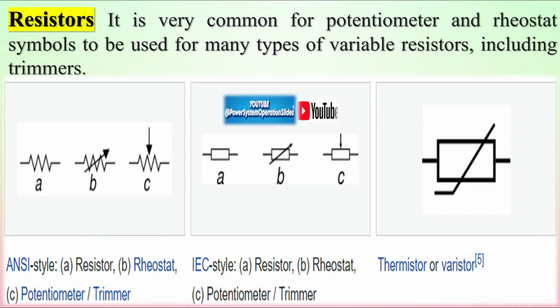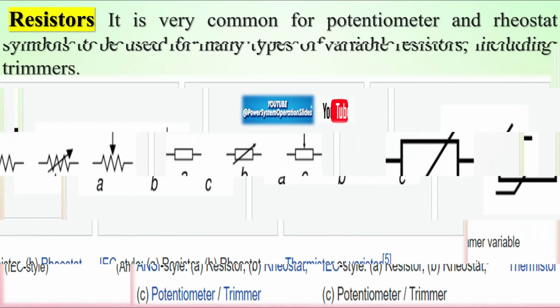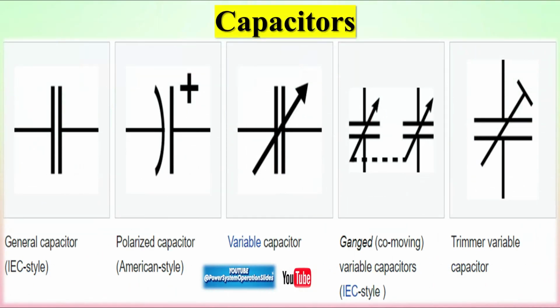Capacitors temporarily store and release electrical energy in a circuit. Illustrated as two parallel lines or one curved line, they regulate voltage and smooth fluctuations. Capacitors are vital for timing and filtering. Diodes allow current to flow in one direction, blocking it in the reverse. Represented as a triangle pointing to a line, they protect circuits and enable rectification. LEDs are a common type of diode.